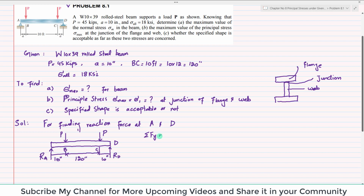Sum of all forces along y direction is equal to 0. There is an upward reaction force Ra, minus P, this one, plus Rd is equal to 0. So Ra plus Rd is equal to 2P. So we have this equation.